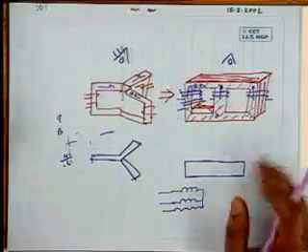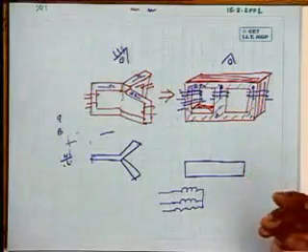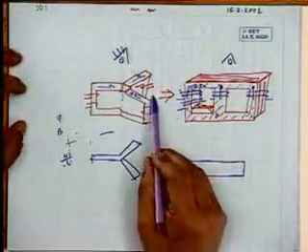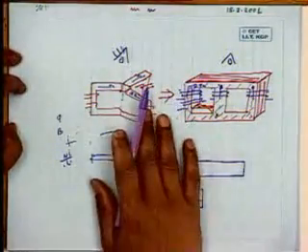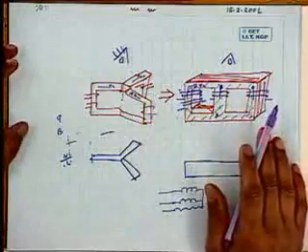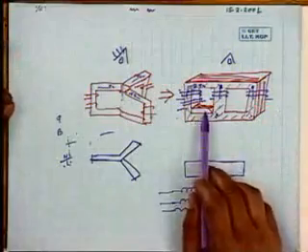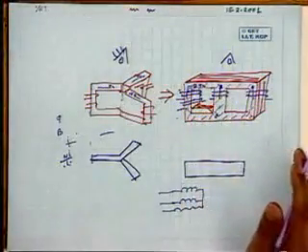Okay? But that is sacrificed. Let that small current be a little bit unbalanced. How does it matter? But you get a great simplification in the construction of the transformer, and it will occupy lesser space, like that. So remember that the magnetizing current in the windings may be different.